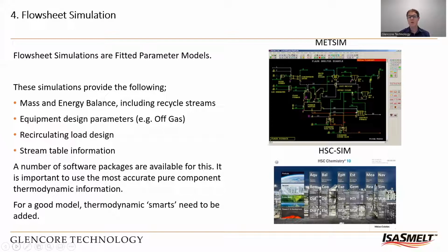So these simulations provide the mass and energy balance, including the recycled streams, the tons in, tons out, the energy going in and out, and tell us all the material flows within the smelter. From this, we can then build up our equipment design parameters, our off-gas system requirements, waste heat boiler sizing, dust collection, things like that. It helps us to fine-tune bleed streams and things like that, so dust leaching plants. It then provides stream table information and parameters which are also used to understand the overall smelting flowsheet.